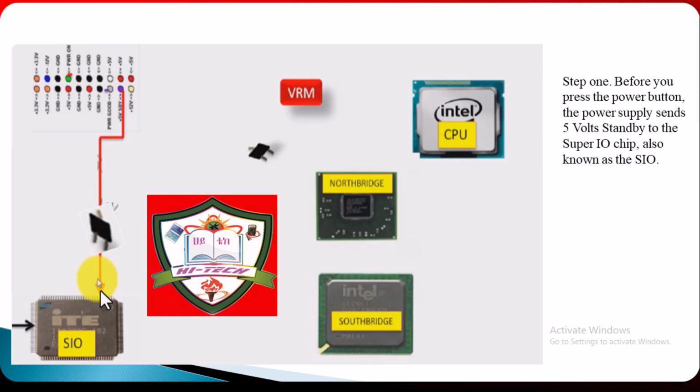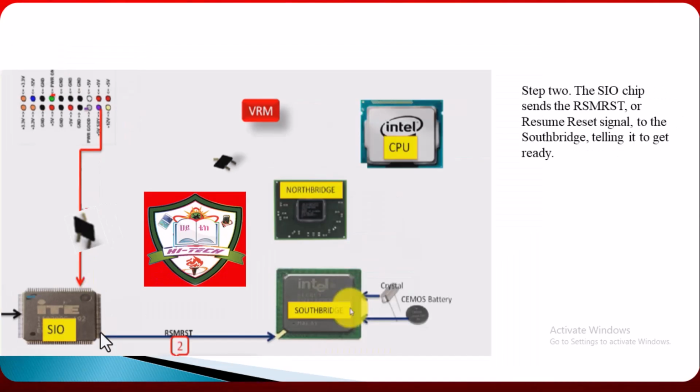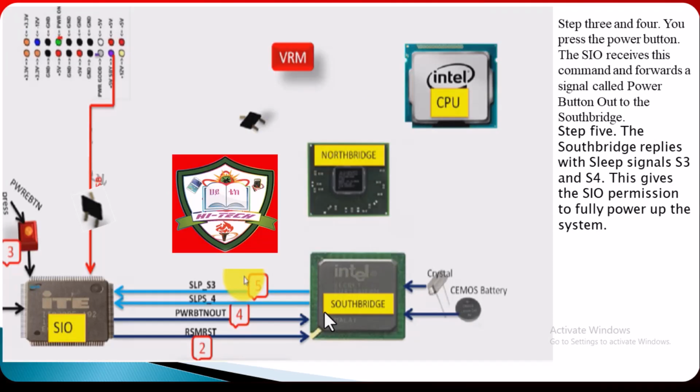So when the computer is in a faulty condition, as a technician you must check this voltage without pressing the power button. At this time the SIO sends a signal to the South Bridge, telling it to get ready.